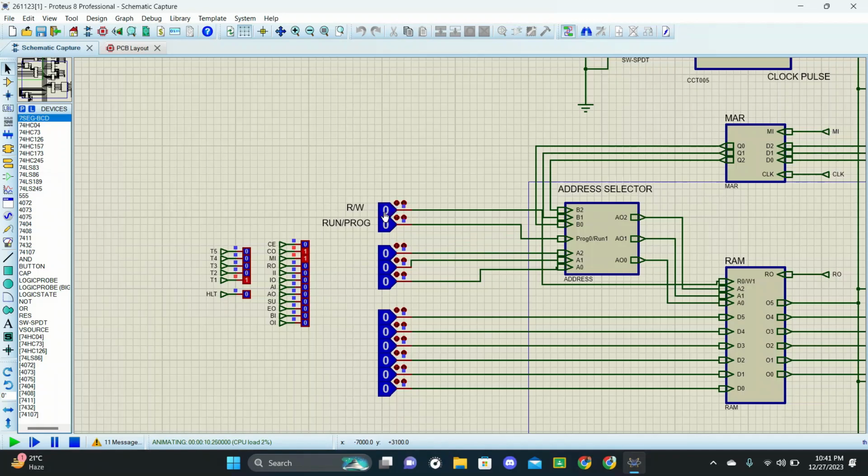So to do an addition operation, firstly, we give 1 here and we keep 0 here and we keep 0 here. Here in the 6-bit number, the first 3 bits denote the opcode and the next 3 bits denote the address. So I am going to give the address to 5, that is 101. Now we give read write here, that is 01 here, and we take here the 1 position.